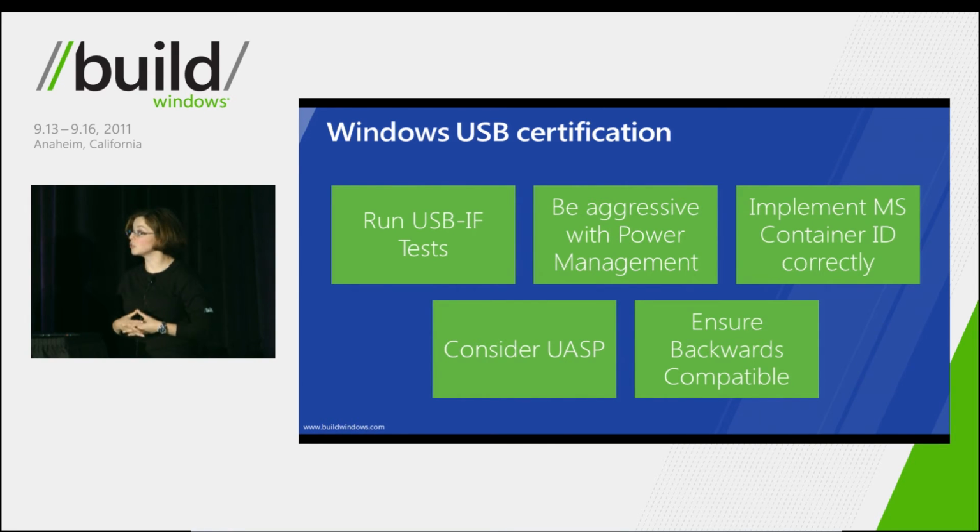If you're considering storage devices and you're looking into USB-attached SCSI protocol, there's a number of tests available in the latest Windows Hardware Certification Kit to help with development of UASP drives. And lastly, backwards compatibility is key. We want to make sure that your devices support both super speed and high speed descriptors and full speed descriptors correctly, so they can work behind different controllers.